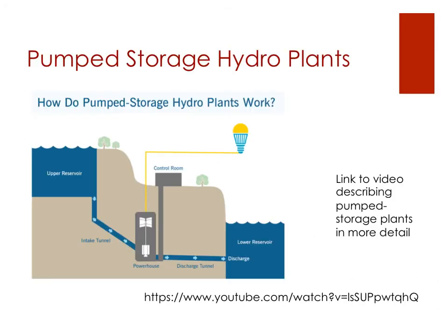In addition to the types of hydro plants you might find at Niagara Falls or those created in Norway, there's also the idea of a pump storage hydro plant. The idea is it's better to keep your power plants working at a continual optimal rate, but as people, we use less power at night. So what do you do with that excess power? The idea is you pump it back up to the top reservoir so that you store it again to be released when you need to.